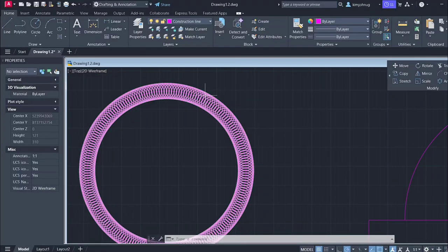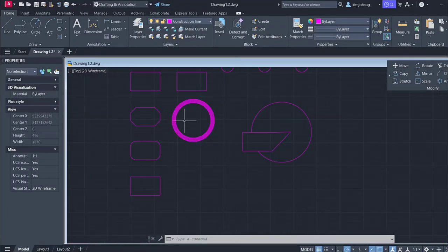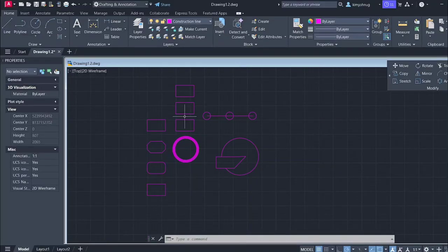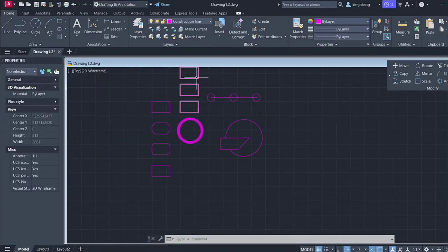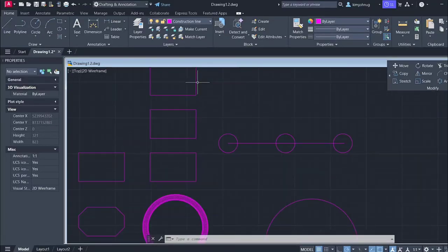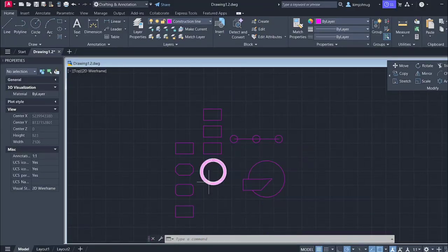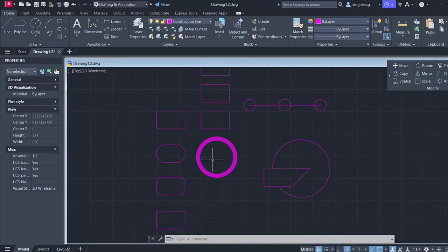It depends on what you want to array around something. If it is rectangular, array them in lines, meaning you don't have to draw the same rectangle again and again if you can just array it. If it is a path array, just array them along the path. If it's a polar array, just array them around the center.